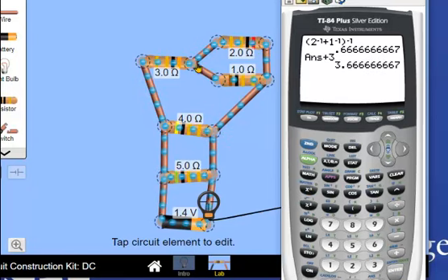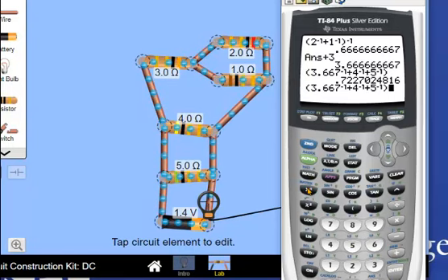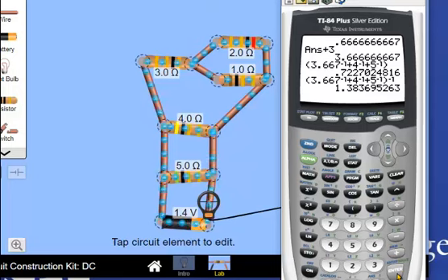And then all of this stuff on top here is in parallel, both with the 4 and the 5. So 3.667 reciprocal plus 4 reciprocal plus 5 reciprocal, parentheses. Oops! The very last thing, I forgot one. There we go, reciprocal. 1.38, just as it should be.